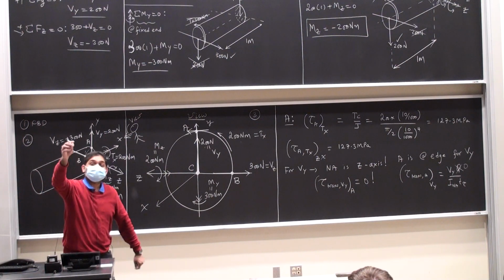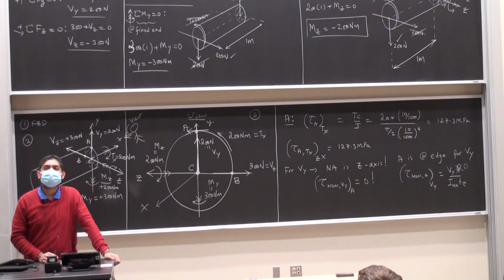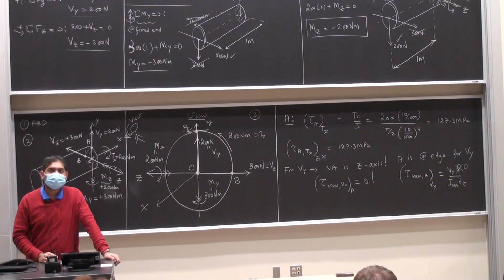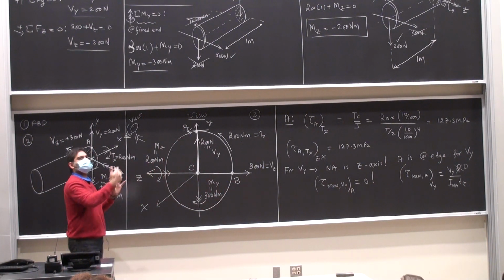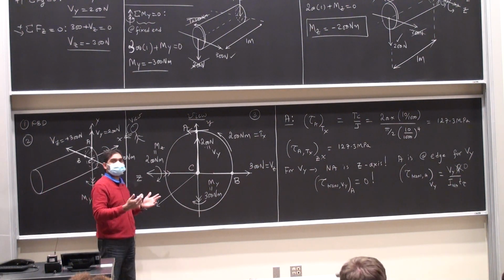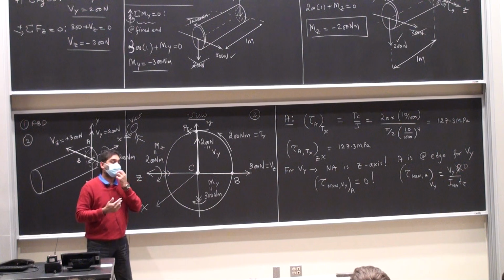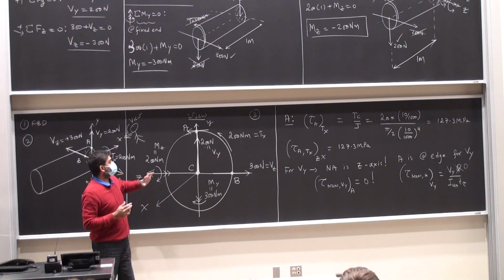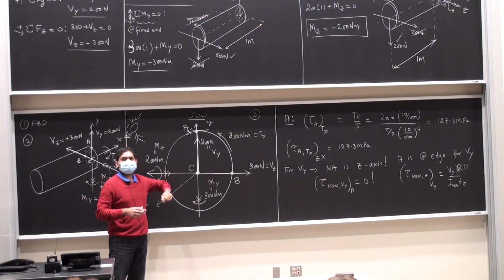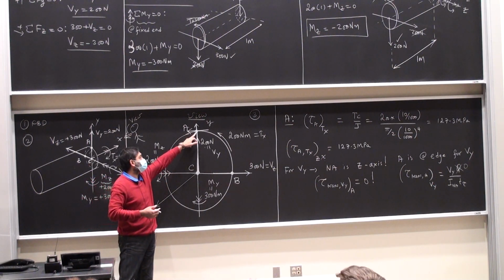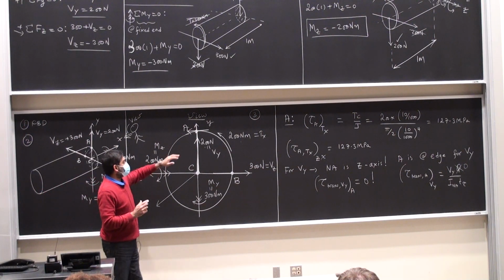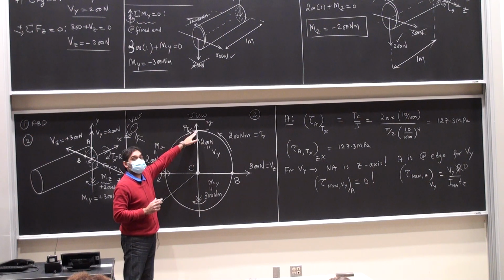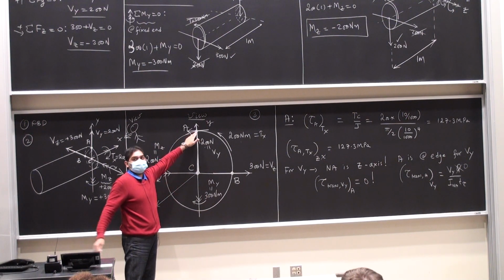Can you explain what's the relationship between the shear stress at point A due to Tx and then the transverse that we just calculated? Oh yes, yes. So here is the deal, right? So this is a problem where there are combined loads acting. I have a torque, I have a shear force, a couple of shear forces, I have bending moments and so on. What we are trying to do is choose a point of interest. Let's say that somebody did a failure analysis and figured out, this is the point where the failure is going to occur. The cracks are going to start propagating from that point. I want to see what is the net stress at that point due to all of these loads acting.